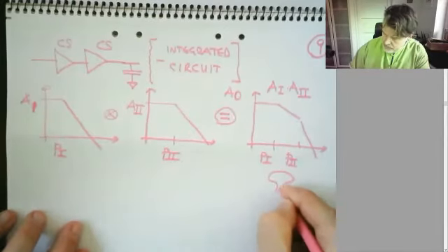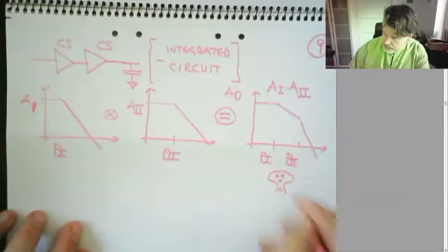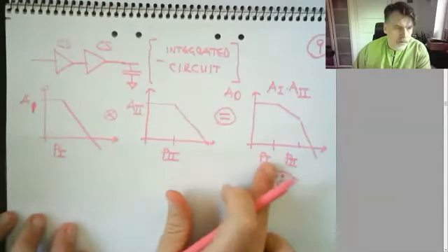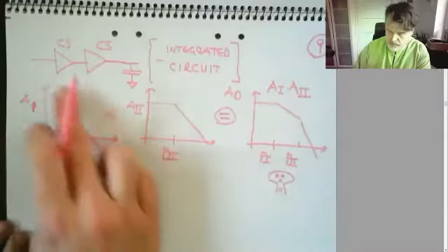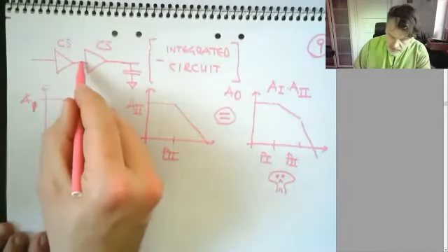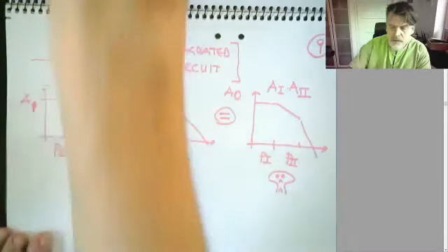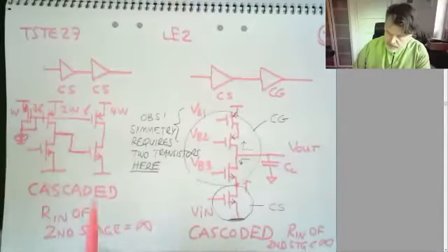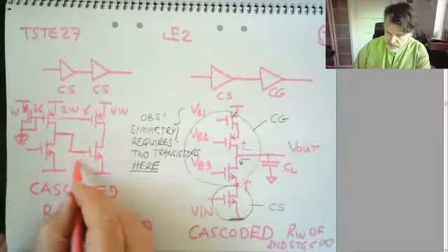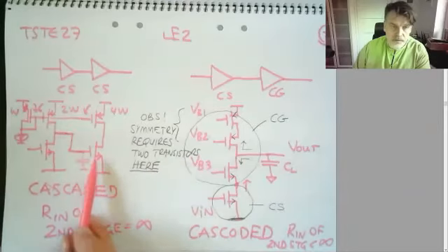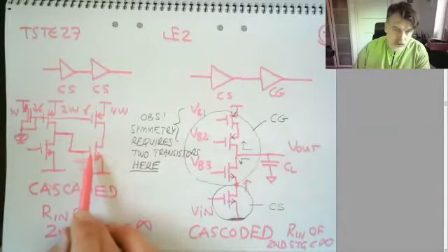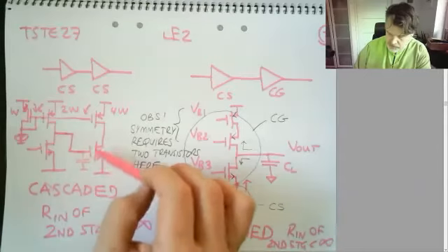So this is sort of a potential issue. We don't know where P1 and P2 are. From this system as I've drawn it, we have a slight capacitance here. If we look at our transistors, it's essentially the capacitance which is here. If you remember from the first lecture, the transistor operates as a capacitive load, more or less. It's the COX in the oxide layer here, which helps to set the current through the amplifier transistor.